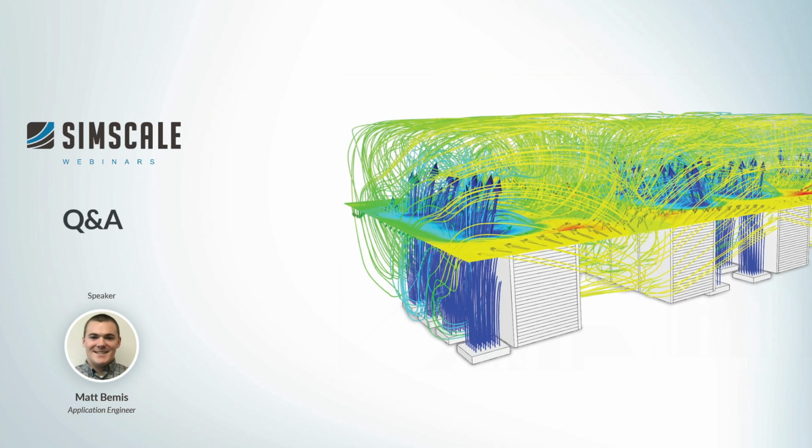Usually where this is most relevant is when there's a high amount of power density at the top of the rack, and down below usually there's blanking or something like that. You can add in that detail. It's always a balance, because you will have to CAD that, and then you'll have to set more boundary conditions, more heat loads. So the answer is yes to that as well.